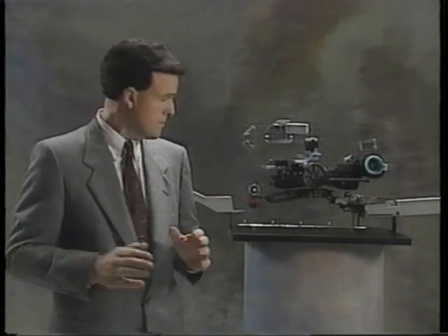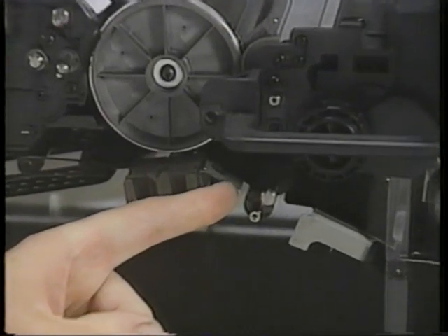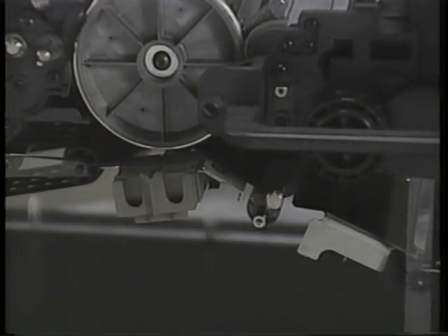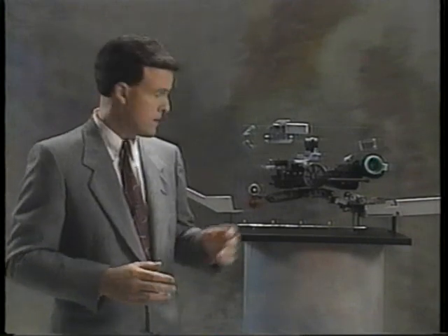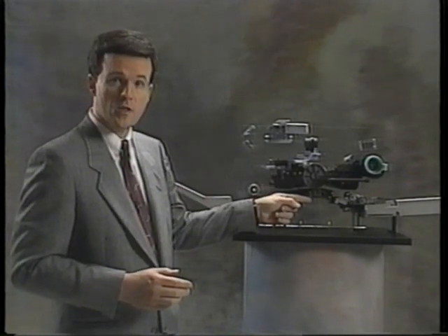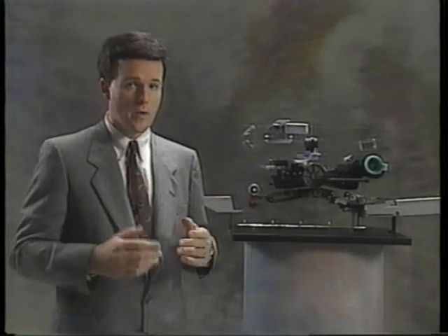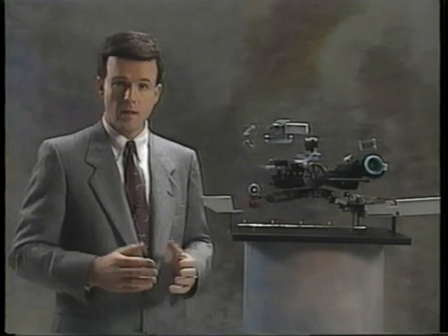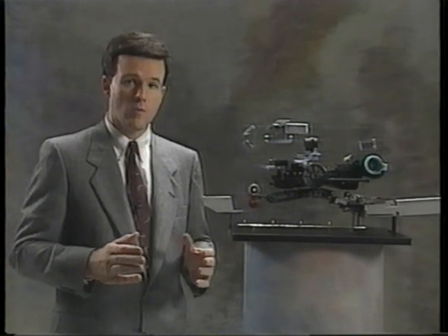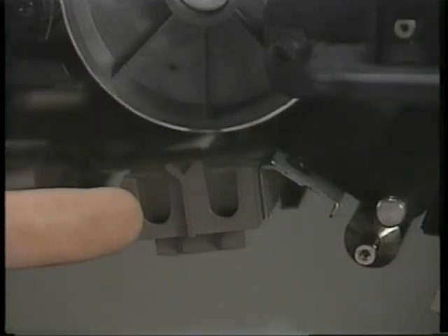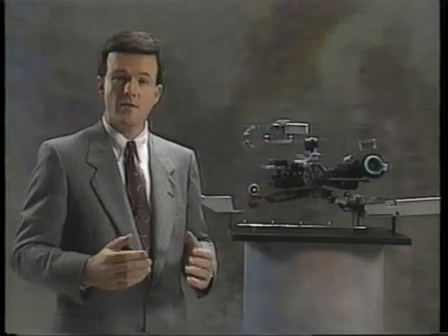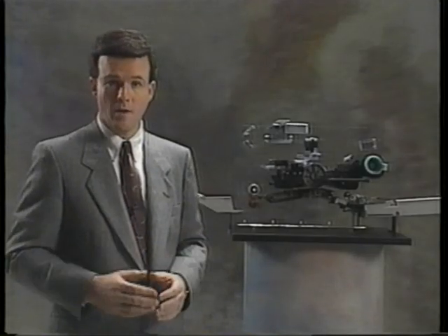At this point, the paper is about here, moving toward the drum, and the developed image is on the photoconductor, approaching the transfer and separation corona units here. These coronas are very similar to the charge corona, metal housings, each with a thin wire running down the center. Like the charge process, transfer and separation rely on the action of electrical fields produced by these corona units. One field pulls the toner onto the paper, and a second field pulls the paper away from the drum.